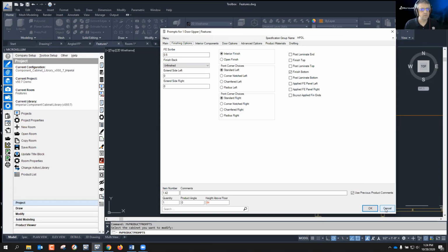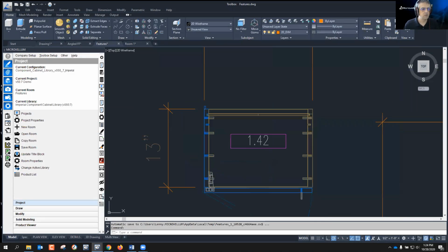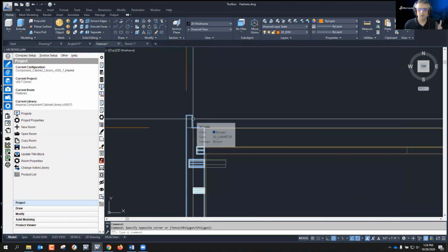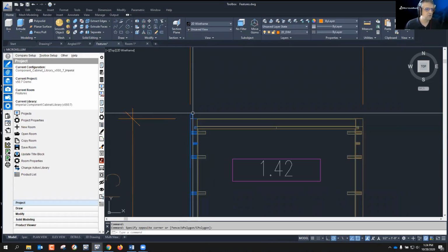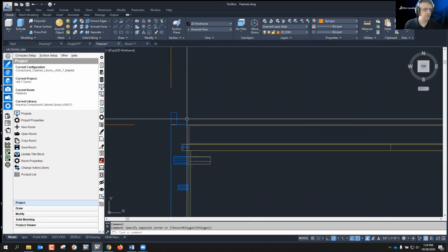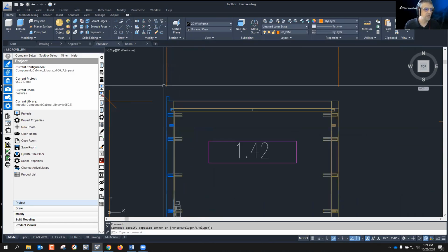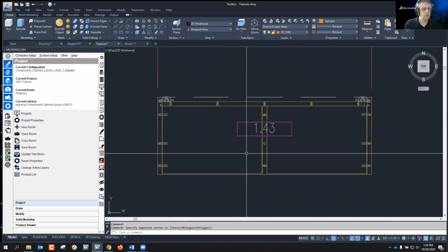And then we have global parameters that will even do a route, a little route here so that the installer, maybe not everybody does that, but some people like to do that to make it easier, makes less sawdust for the installer. And there's variables that control how deep that is and whether or not you even want it on or off, but you can kind of see there at the back of the cabinet. So that scribe route feature is doing better, or it's in there.